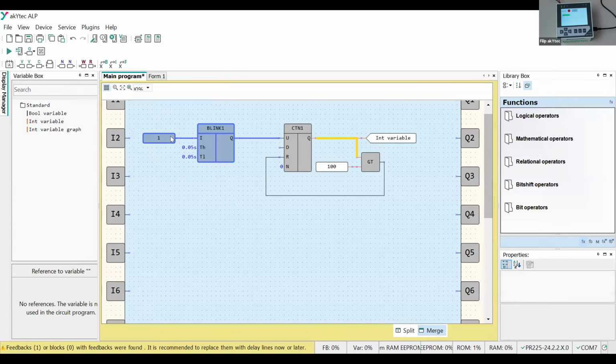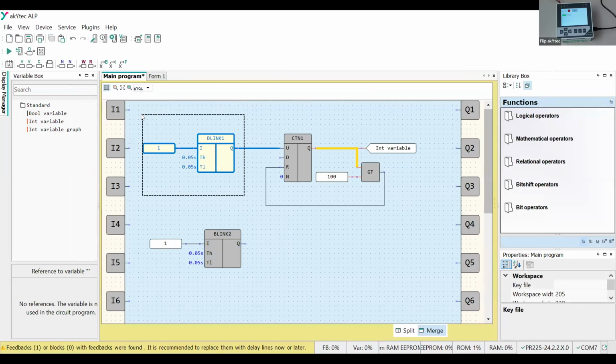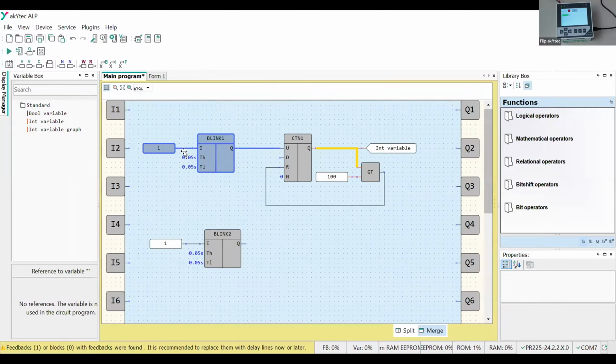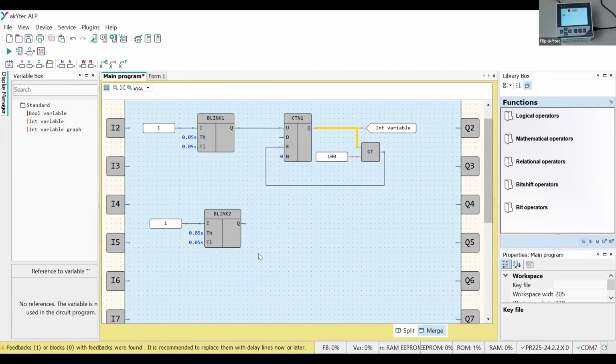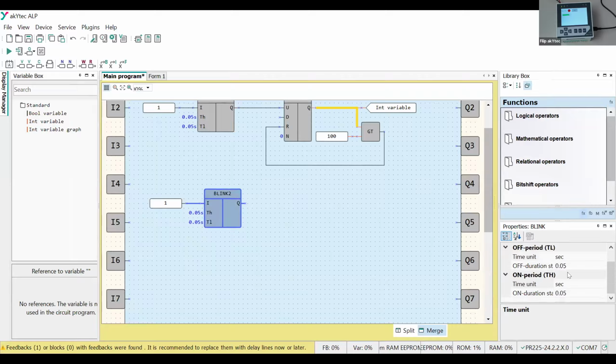For this, we'll also need a blinking block. So here, just now I selected the blocks that I want and did Control C and then Control V, so I just copied it faster. So we want for every, let's say, 2 seconds, so off duration would be 1 and on duration will be 1, to have value 20, and then for 1 second value 0.